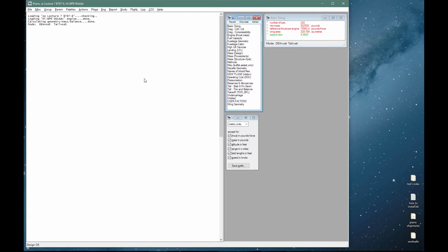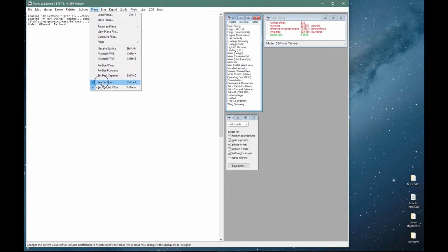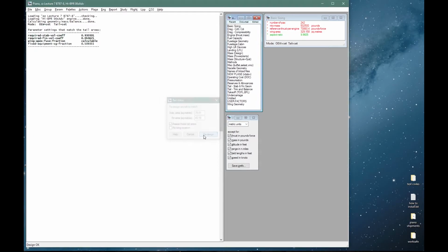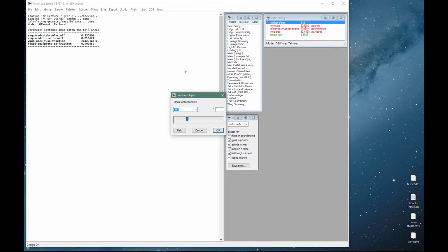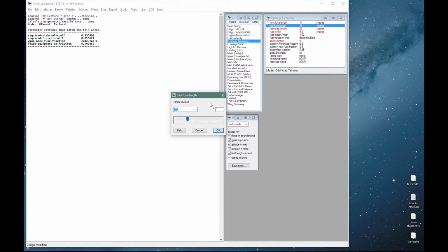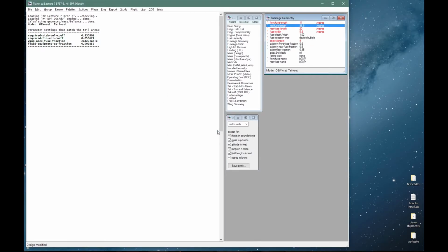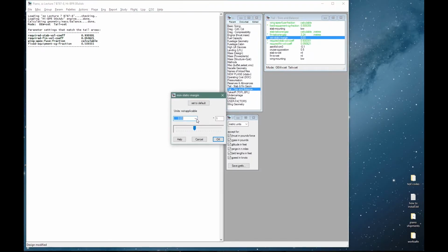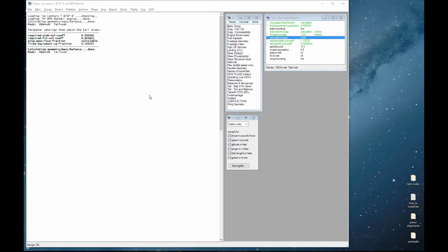First, let's free up the wing location. Set our passenger count to 330 and increase our mid-fuselage length by 11.5 meters. Some secondary settings we just can't know for sure. For example, with such a long fuselage, we might be a little bit conservative with CG and loading arrangements and reset our nominal static margin back to 5%. And let's look at the aircraft.